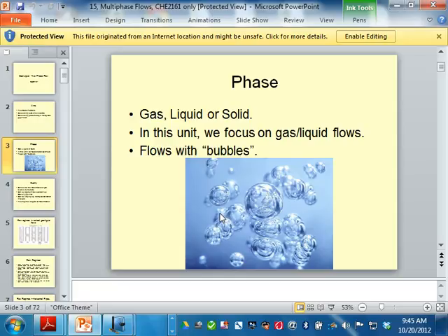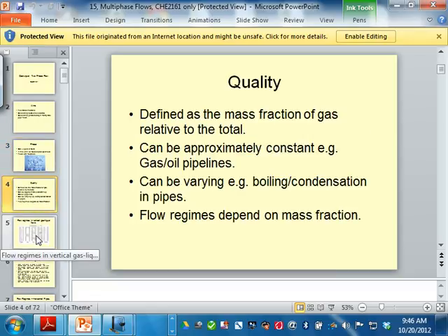Depending on your flow conditions and what the ratios are, you might get one phase dominating the other. You can have gas being the continuous phase with a mist of liquid inside, or you can have the other extreme: water is the continuous phase and you have small droplets of gas inside, depending on your mass ratios.